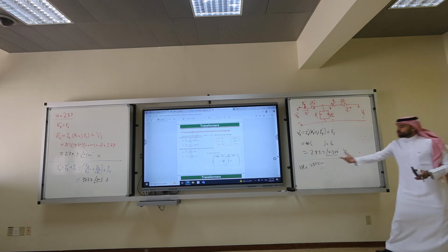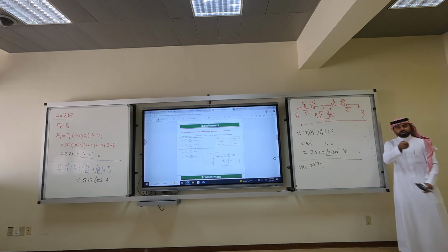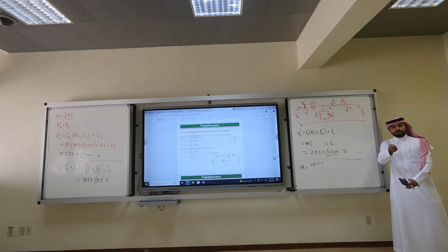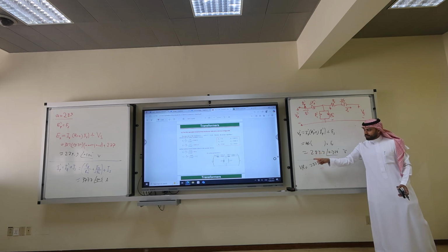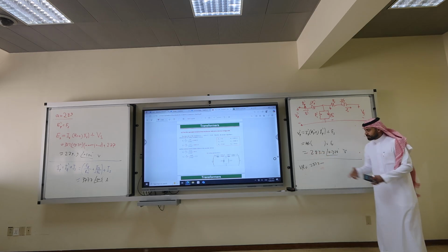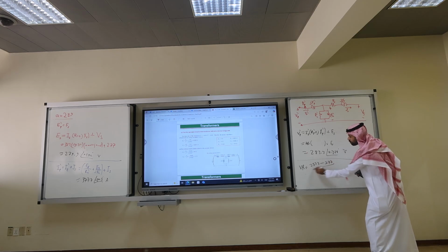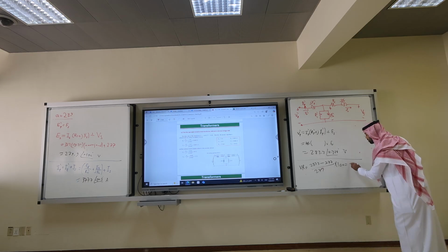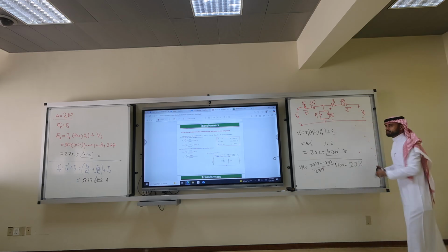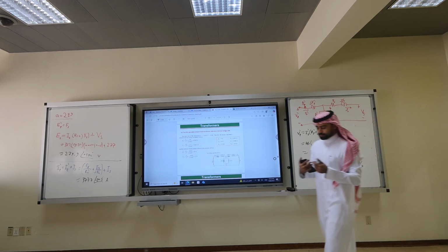Minus, this is the no load voltage. What is V full load? Connect back the refrigerator. Now the load will have 277. And the primary reflected would still have the 283. So minus 277 over 277 times 100, and you should get 2.2%. This is the proper percentage. Okay?